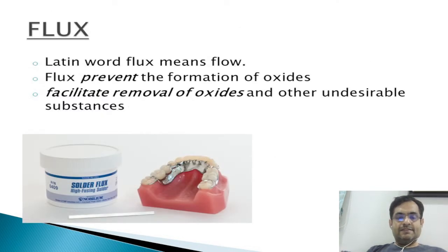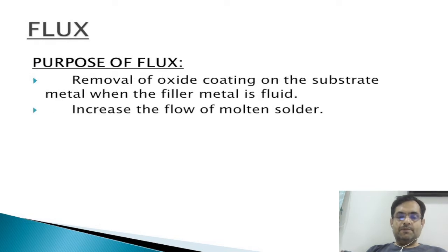Next comes the flux. The Latin word flux means flow. Flux prevents the formation of oxides. It facilitates removal of oxides and other undesirable substances, and it increases the flowability of the solder metal over the substrate metal.